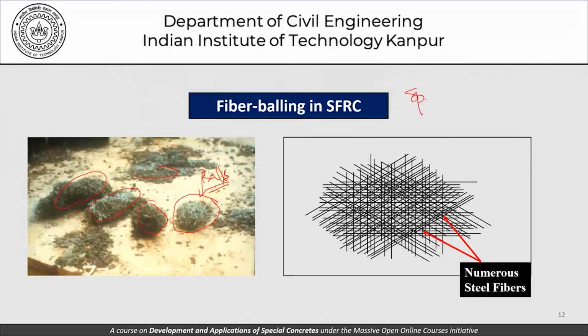One should remember that the specific gravity of steel is 7.8, and this is much heavier than all the constituents as far as concrete is concerned, and therefore there could be a tendency of these fibers to promote segregation, of settling down in the concrete matrix and not remain uniformly distributed throughout the matrix as we originally thought they should. Keep that in mind, especially for steel fibers, because they're heavy. The other fibers are not as heavy. It's probably easier, but if the fibers become very light, then again there is a problem, because then they tend to float.